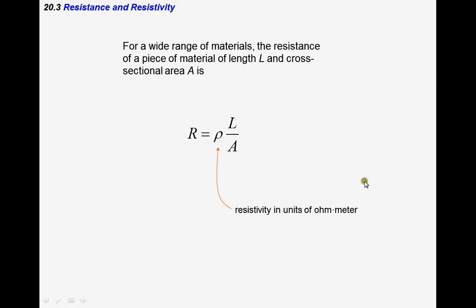They all have different amounts of resistance, and then if we design the device, we have the length. Resistance will increase the longer it is, and resistance will decrease as the area, the thickness of the device, increases. What we'd like is to have lightweight wires made of relatively cheap material that have low resistance.